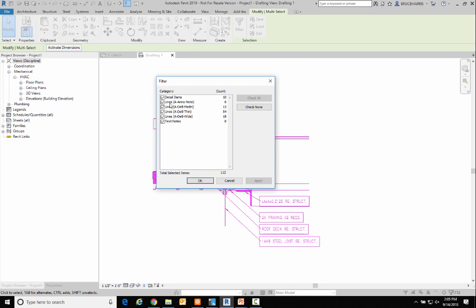So I've got lines, and in parentheses, A-ANO-NOTE, A-DETAIL-MEDIUM, A-DETAIL-THIN. Those are the layers that the line work came off of in AutoCAD. So if your AutoCAD details are layered well, and you know what each of the layers is supposed to be used for, it makes your life a whole lot easier.